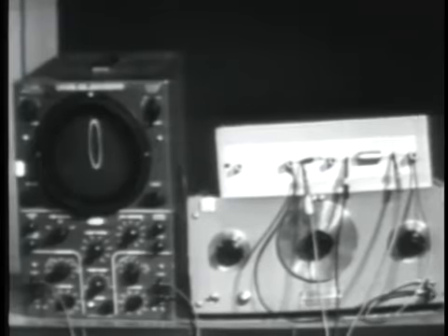Now, we have the first one on here, and the first Lissajous pattern is simply an oval which indicates two voltages exactly 90 degrees out of phase. But you may say, I thought two voltages 90 degrees out of phase were supposed to give me a circle like this. Well, true, it would be a perfect circle if the two voltages were out of phase by exactly 90 degrees and equal in amplitude. However, the two voltages in our problem are not equal in amplitude. Remember, ER is greater in amplitude than EC.